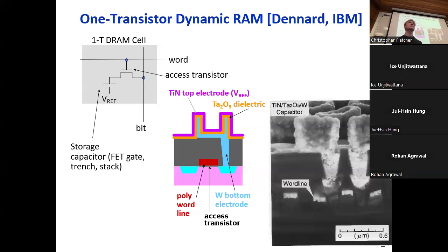Recall from last time we spoke briefly about core memory and how each bit of core memory was stored in one of these toroid magnets that were hand-strung with perpendicular wires. These hand-strung toroid magnets were not very small and not very dense. This toroid magnet component was quite large. And so what we're going to try to do is scale our memory down and see how few components that can be scaled along with process technology and automatically fabricated, how low can we get, so to speak, to design as dense a memory as possible.